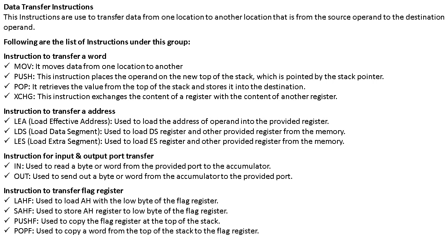Instruction to transfer the flag register. LAHF, used to load AH, that is the higher order, with the low byte of the flag register. SAHF, used to store the higher order register to the low byte of the flag register. PUSHF, used to copy the flag register to the top of the stack. POPF, used to copy a word from the top of the stack to the flag register.